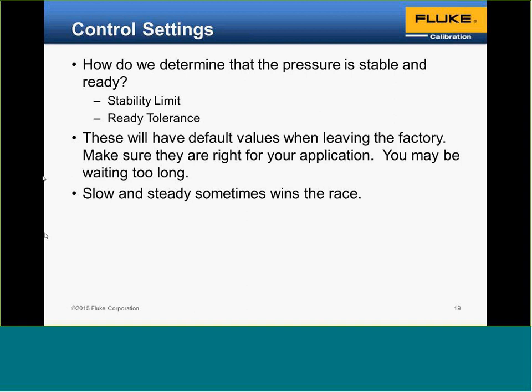Now when I say slow, I'm not talking about 5 minutes, I'm saying 30 to 45 seconds to set point. That is still relatively much quicker than using a manual setup where you're controlling the pressure with a needle valve or a hand pump.